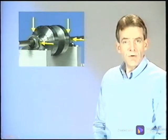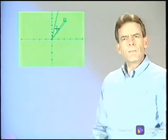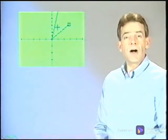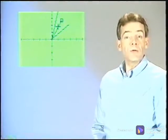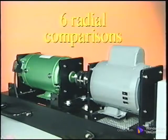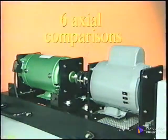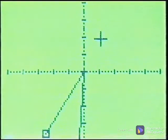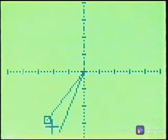Static phase measurements provide another tool for diagnosing many machinery conditions. Remember that because phase measurements provide amount and direction, they can be displayed as vectors to show the machine's motion. Use the six phase comparisons in the radial direction and the six phase comparisons in the axial direction. Be sure to take into consideration the orientation of the sensor. The directional phase comparisons, as well as some erratic phase conditions, point to specific machinery faults.